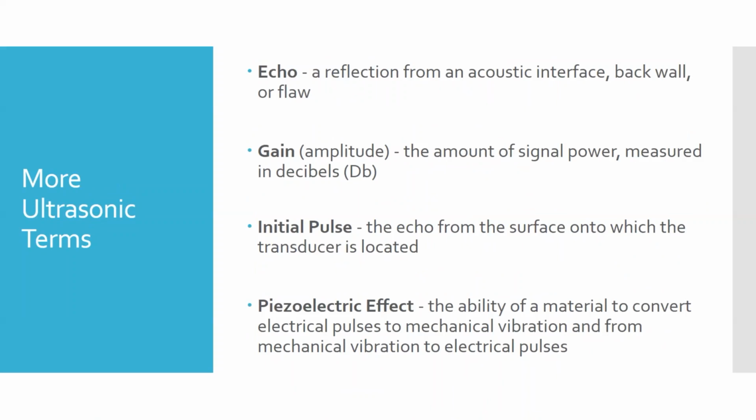The flip side to that is a piezoelectric crystal works in the opposite direction as well. So if a piezoelectric crystal is subject to vibration, it will produce an alternating current sine wave in the wires that are hooked up to it. So we can use it to both generate our ultrasound and to sense the ultrasound. It works as both kind of a speaker and a microphone, whether you put power in or not.